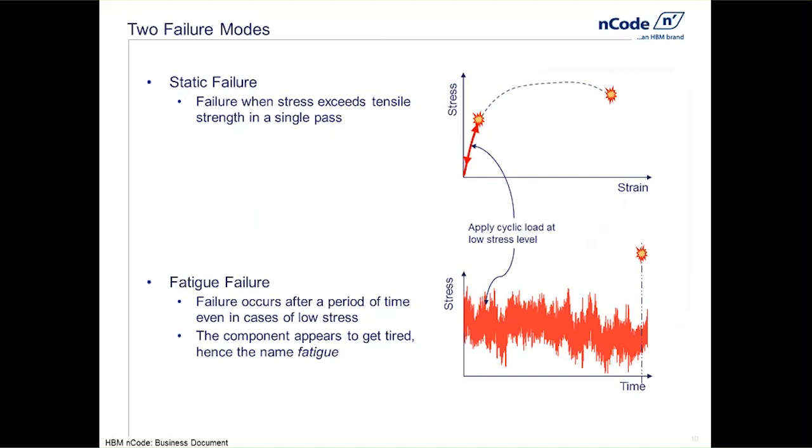the dotted line, we see that there's this linear portion of the stress strain curve. Okay, this is when stress and strain are linearly related through Young's modulus. At the point where it starts to curve a little bit, that's when yielding occurs. And if we continue to pull and apply force to our part, we start to see large strain changes for relatively small stress changes.